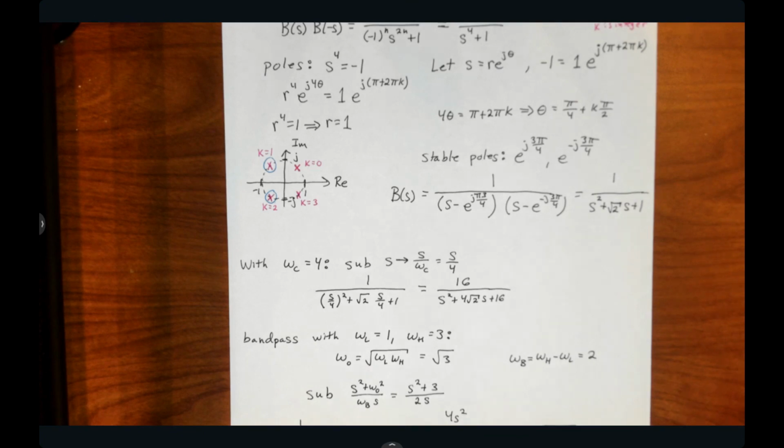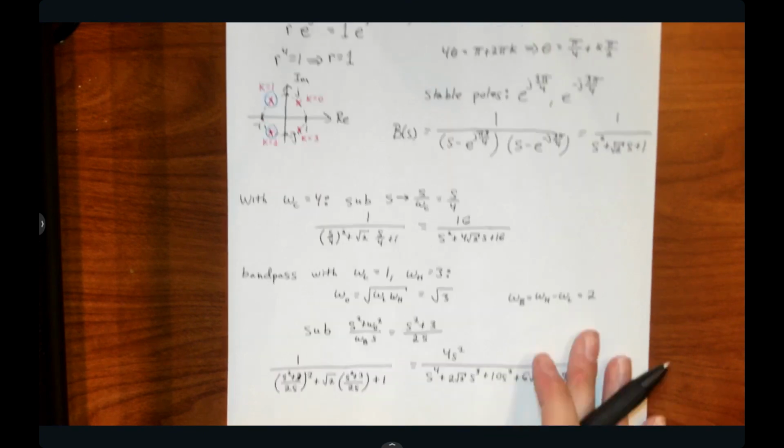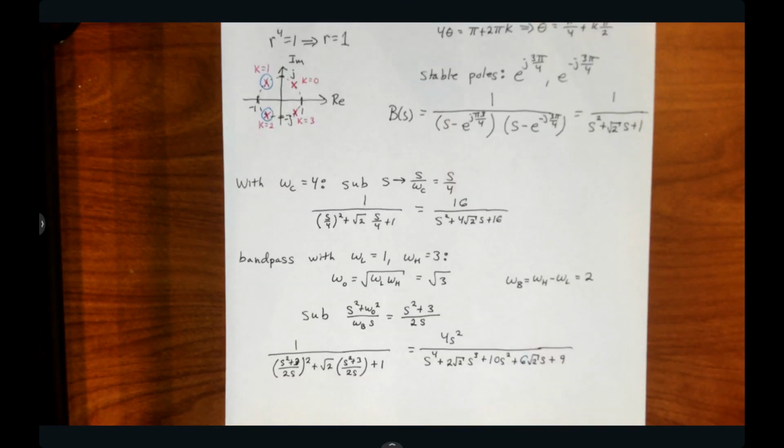And that Butterworth filter is going to be maximally flat at omega equals 0 and have a cutoff of around minus 3 dB. As I said, there's other approximations that prioritize other features to try and get closer to the filter design that you want. But for purposes of this class, we're just looking at the Butterworth filter.